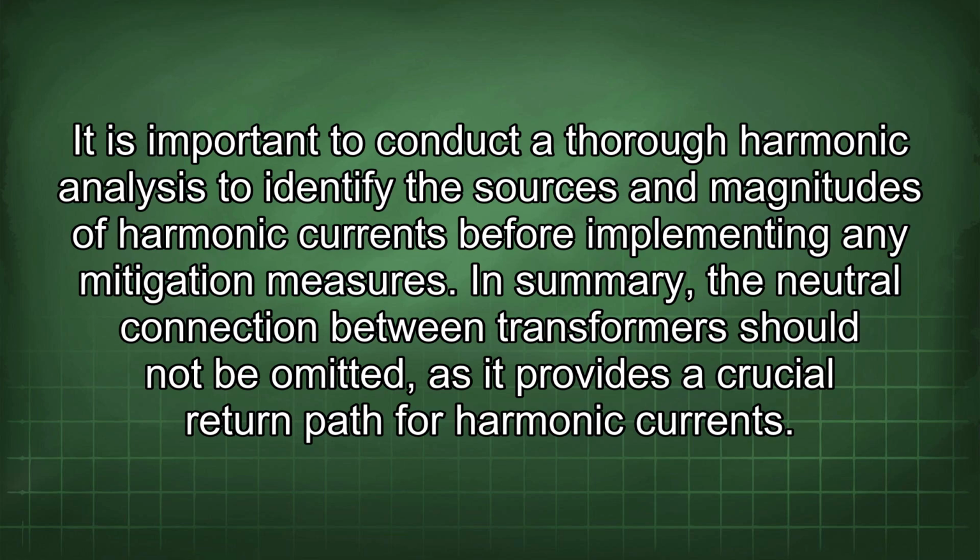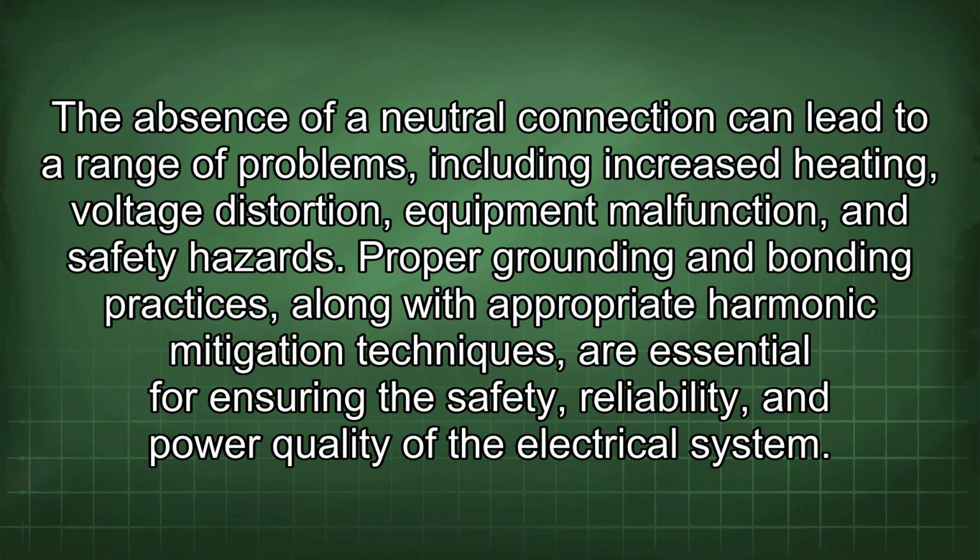In summary, the neutral connection between transformers should not be omitted, as it provides a crucial return path for harmonic currents. The absence of a neutral connection can lead to a range of problems, including increased heating, voltage distortion, equipment malfunction, and safety hazards. Proper grounding and bonding practices, along with appropriate harmonic mitigation techniques, are essential for ensuring the safety, reliability, and power quality of the electrical system.